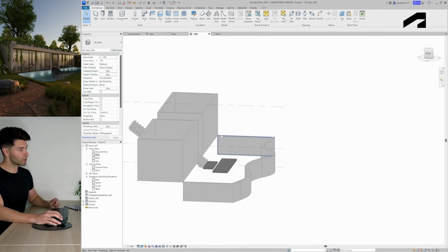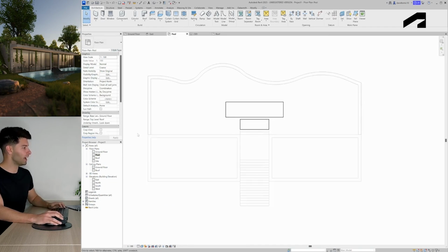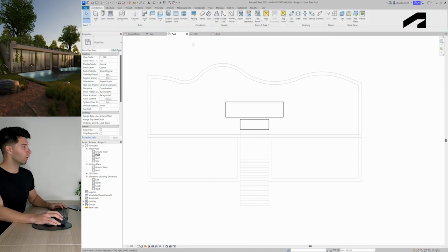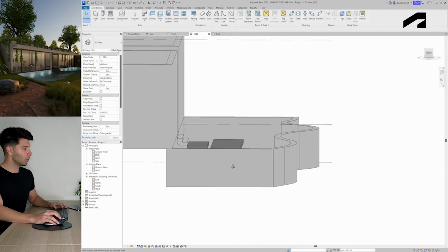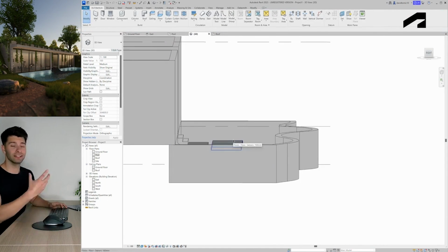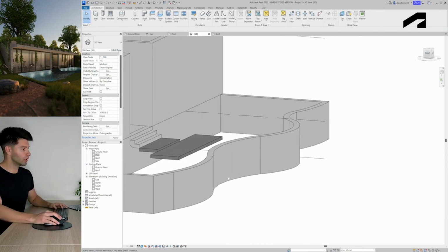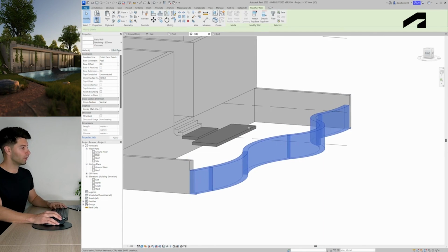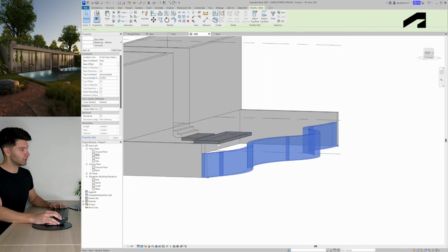So now we see our pool structure created and the back missing. Let's jump back into pool, come back into our wall, simply finish off the base of that wall and come back into 3D. What we're gonna notice is that our stairs are again a little bit too low and not really working for us. So we're gonna hold the control button, select our curved walls. We simply now wanna reduce the height by 521 to actually reduce it to the height of that step there.